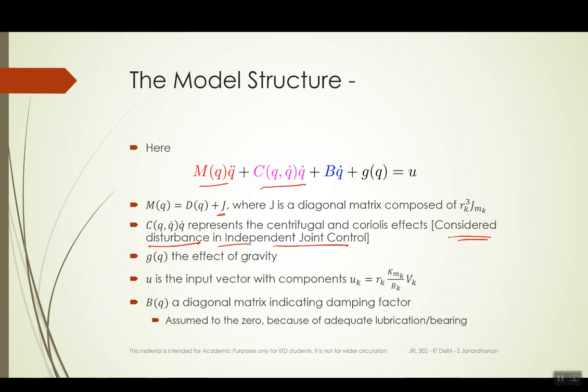And to compensate for this disturbance, in the computed torque control, we had incorporated this effect as a nonlinear control. So we were trying to calculate, we were trying to figure out what this C of q, q dot was, and we gave C q dot as an input, as a part of the input.